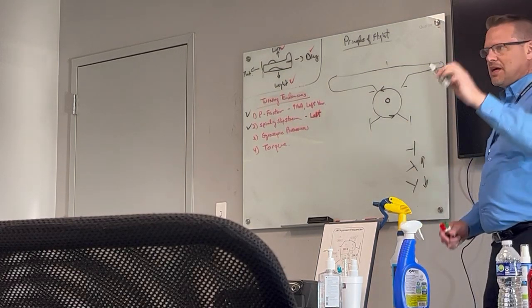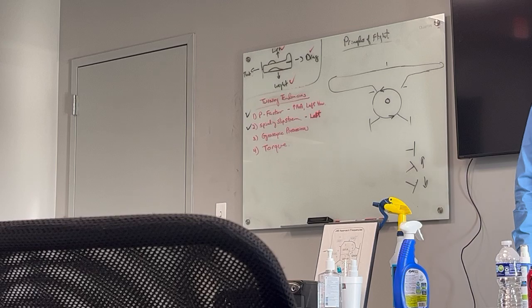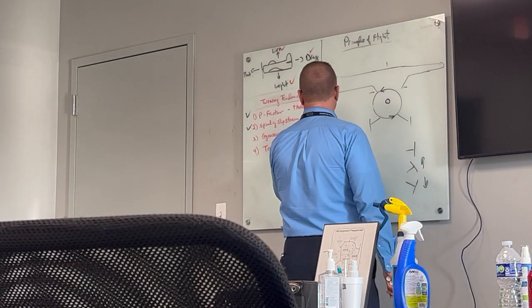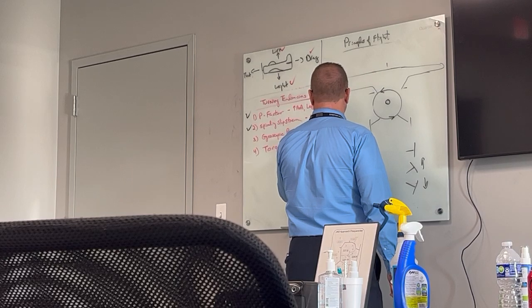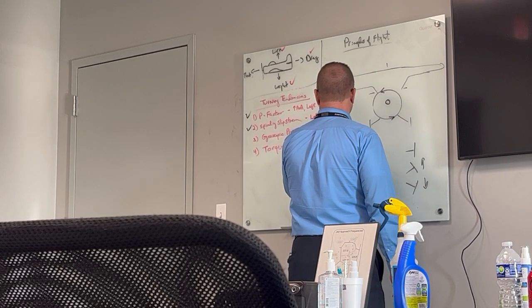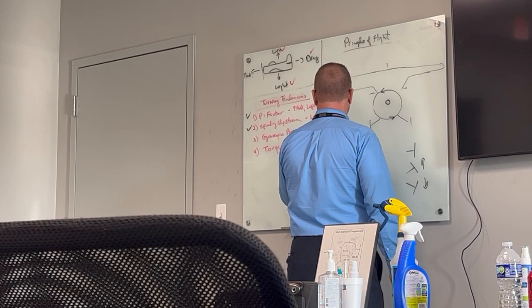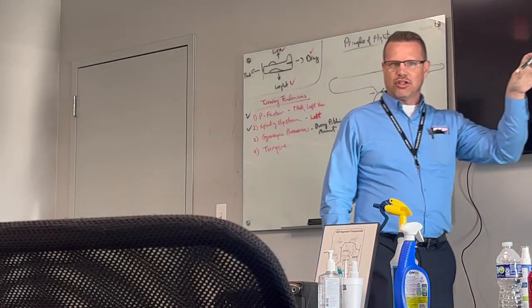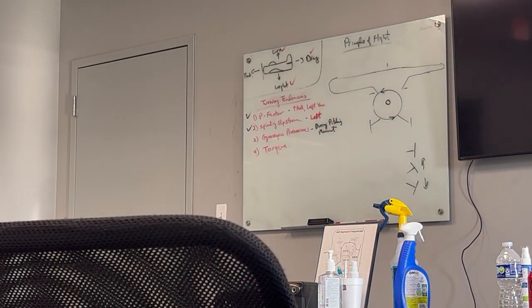Now, only during the time that the pitching moment is occurring do we have gyroscopic precession. So, during the pitching moment. And what do I mean by pitching moment? When the pitching is actually occurring. Okay, so in other words, if I'm straight and level and I pitch to 15 degrees nose up, as I'm pitching to 15 degrees nose up, that's the moment itself. So I'm feeling gyroscopic precession.